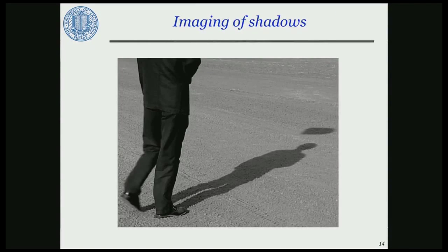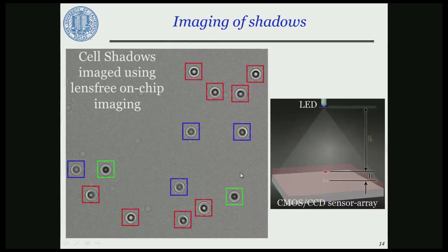So because of the lack of optical components or an imaging system, these kinds of microscopes that utilize the CMOS or CCD taken from a digital camera, they literally are starting with sampling of shadows. If you take a CMOS off a mobile phone, remove the lens, you have this silicon chip which has, let's say, 5 to 10 megapixels. If you place a sample right on it, where the distance between the sample to sensor is, let's say, sub-millimeter typically, you'll be capturing these diffraction patterns, these shadows of the specimen, and it could work like a cytometer based on the signature.